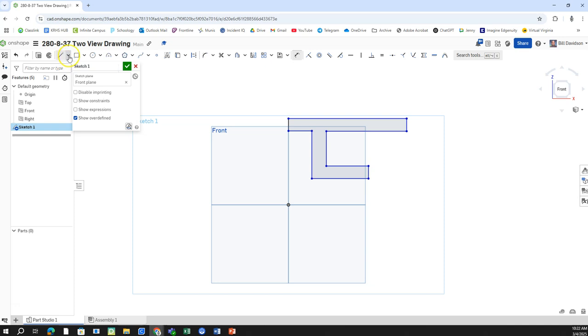Oh, before I do that, since I'm going to revolve it, I need to revolve it around a center line. So I'm going to go here, click a midpoint line, and go for my origin point. I like to do the midpoint line because it attaches it to be centered on that, and I can find it easily later on. But I also want to click construction and change this line to a construction line, so it doesn't get used later on, and it's not an entity that needs to be dimensioned or anything.